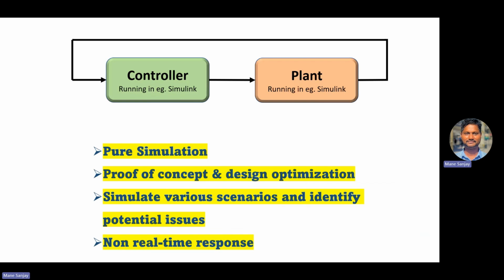And lastly, when I talk about the block diagram, here is a controller which is basically running in the Simulink. And here again, your plant model where you can feed input and output. In the controller, you have your entire algorithm written in Stateflow or in Simulink, or in the virtual interface in LabVIEW or in AMESim. So here you simulate the entire controller and you feed the output of your controller to the plant model, whatever model you want to have simulated here. Again, the output of that plant model is fed back in the control loop to the controller.